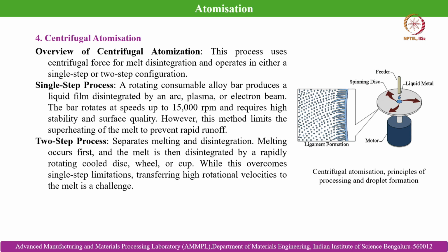In case of single step, a rotating consumable alloy bar produces a liquid film disintegrated by an arc plasma or electron beam. So, it is basically the electrode which is undergoing a centrifugal motion, and that is responsible for melt formation and also exerts centrifugal force on the liquid melt, and facilitates its disintegration in the form of droplets.